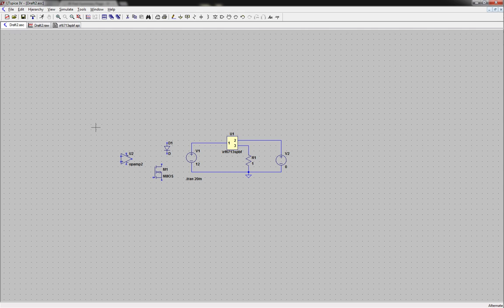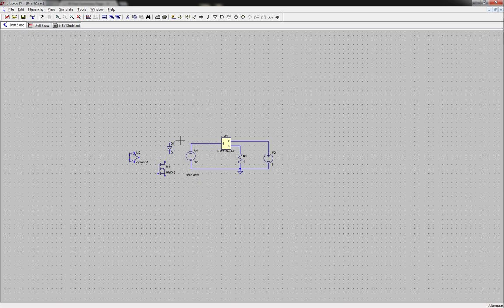But again, it's all just ASCII text. So whether it's a .lib or .spi or .cir, or there's like an S-something, it's not SPI, but something else, SPC or something like that, no matter what file extension it has, it's just text. You can always resave it or rename it to something that LTSpice will recognize. Or you can even just cut and paste it into Notepad and save it as a .cir or .spi or whatever LTSpice recognizes. So keep that all in mind.